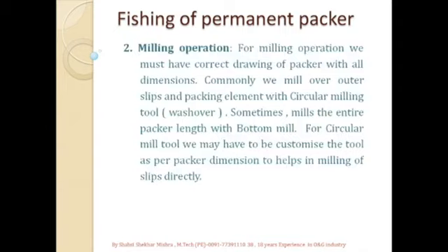So for milling operation, we must have a correct drawing of the packer with all dimensions. Means it must have the correct OD, ID, the position of slips, the packer element, the mandrel, and all this. Because the drawing is very important for the design of the washover or selection of the circular milling tool, because we have to run such that this washover shoe directly lands on the slip.